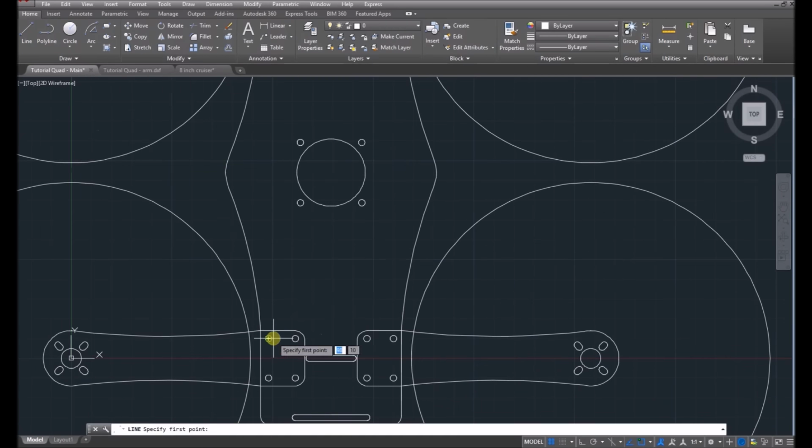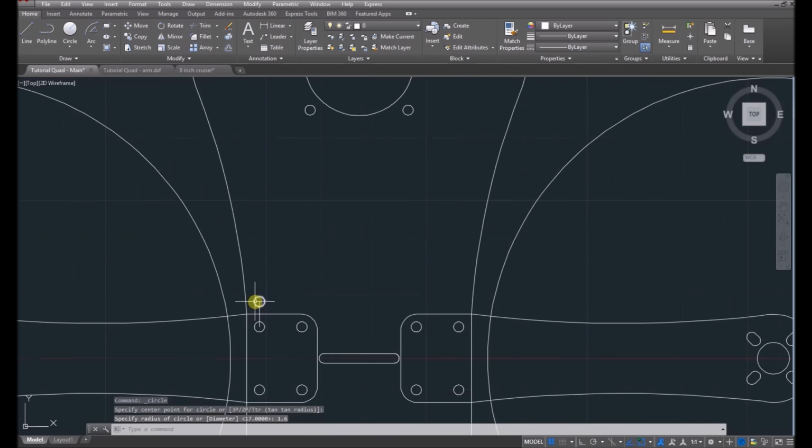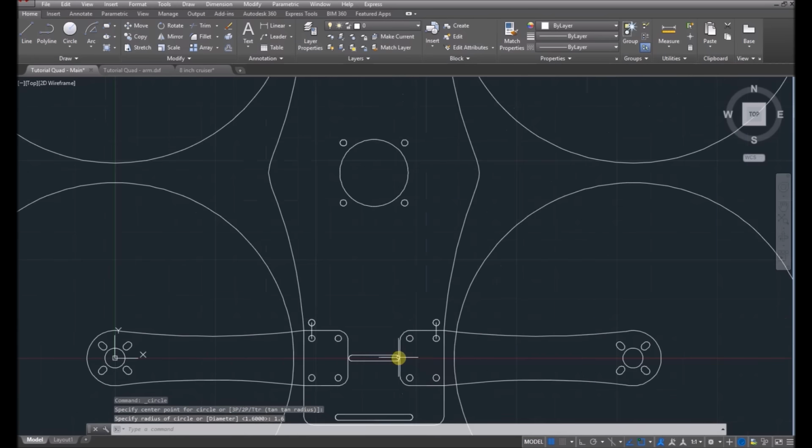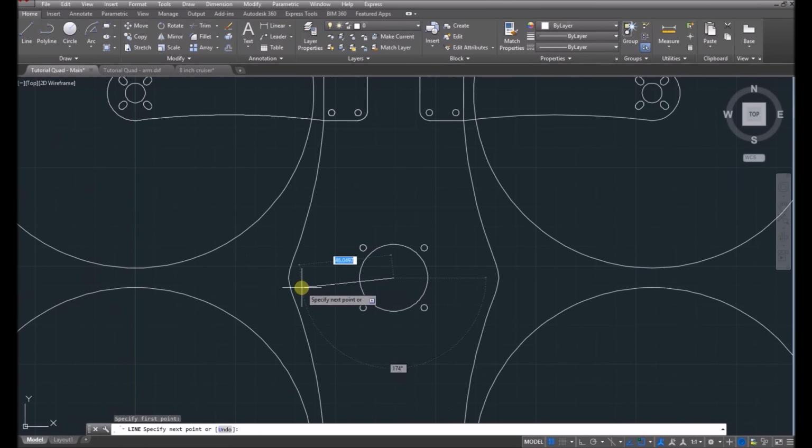Oops, I hit F1, which is help. Often I do that instead of hitting escape. And I'm going to make a 1.6mm hole there. So I'll come up here and go 8, and a 1.6mm hole. Now, you might want to think about how many standoffs you're going to have. Let's just go 6 for this demonstration, because that's easy. Now where are we going to have this one? Let's go 40, 46 mil. Looks like a pretty good spot.